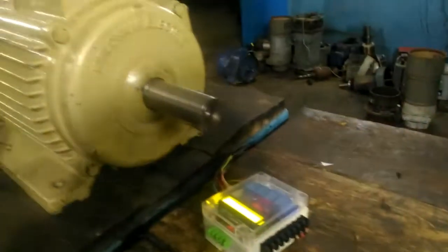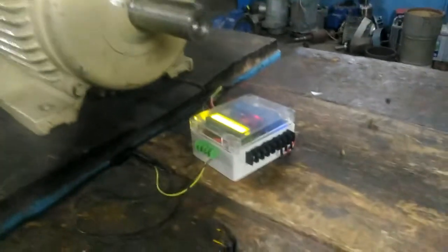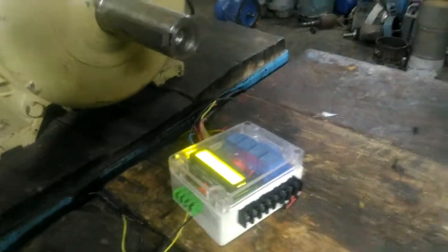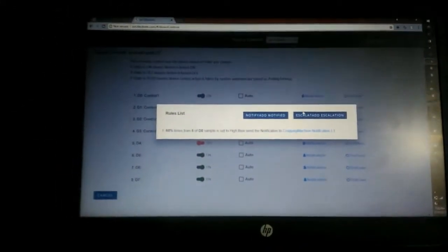Again, we had 4 different bad readings, and then we could see that that particular motor is shut down automatically. And it goes to a manual state until an operator puts it back again. So we had a bad formula, or sorry, we had a lesser value put. That's the reason it is trying to take control of the motor. Otherwise, it seems to be fine.